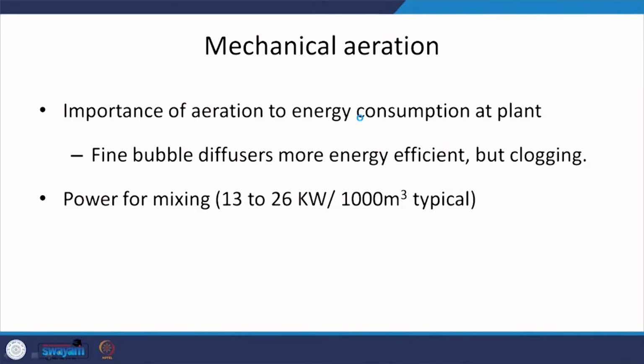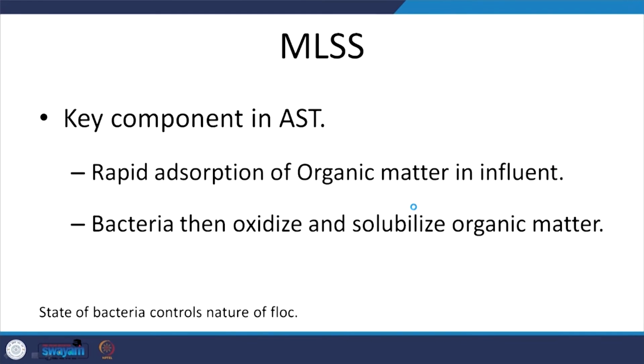So, mechanical aeration, as I mentioned: fine bubble diffusers are more energy efficient, typically with greater oxygen transfer efficiency, but maintenance is an issue due to clogging. Power for mixing: you can understand the relevant energy requirements from typical power values. Now we will come across a term, I think I might have used it earlier: mixed liquor suspended solids, mixed liquor suspended solids.